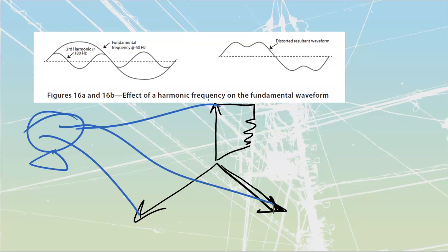You're also going to get unwanted heat because this one here is so small it's not doing much, which means that this one and this one over here are going to have to do more than their share. They're going to have to pull along a little bit harder, which means we are going to see more heat because they're pulling more current. Under our NEMA system, which is what our motors are mostly designed under, we do have IEC, but most of our motors are still NEMA, we're not supposed to be operating at voltage imbalances above 5%.